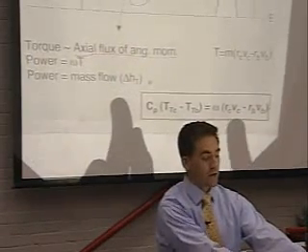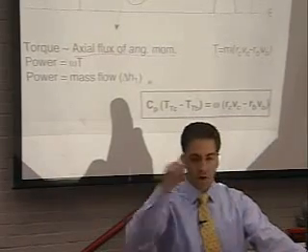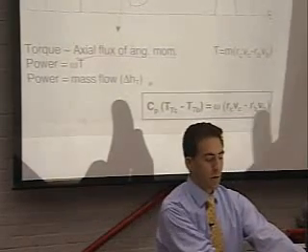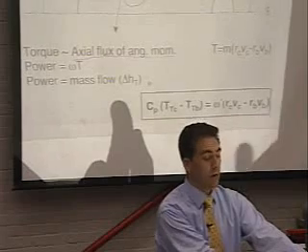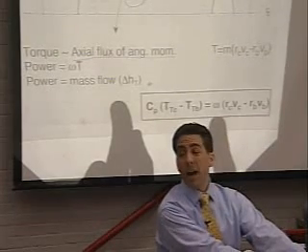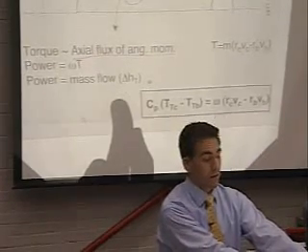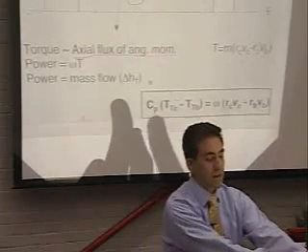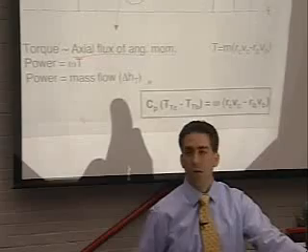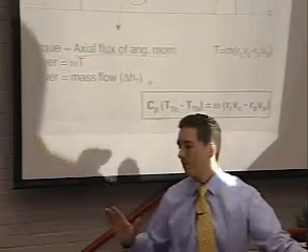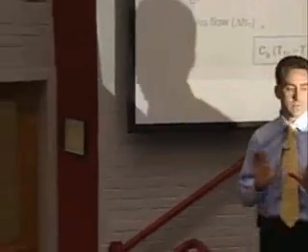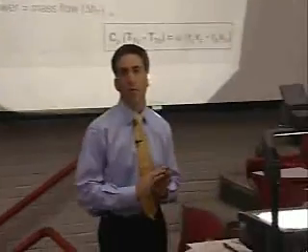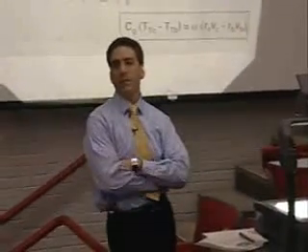If you change the velocity tangentially with a blade row, and you have that blade row moving, you get a change in the stagnation temperature. That's the enthalpy, c_p delta T total. And so that's what we got to last lecture. Are there questions about that before we go on to the blades themselves?